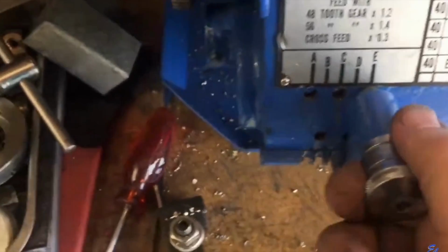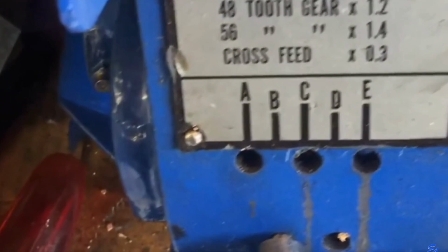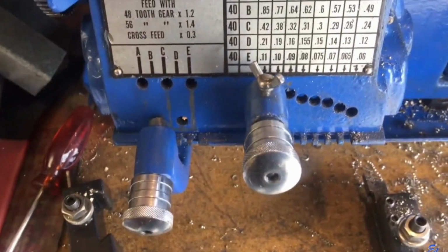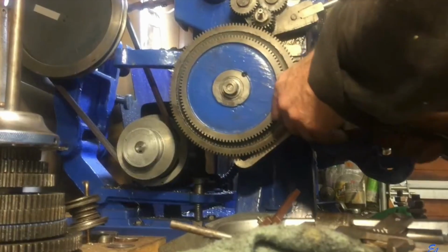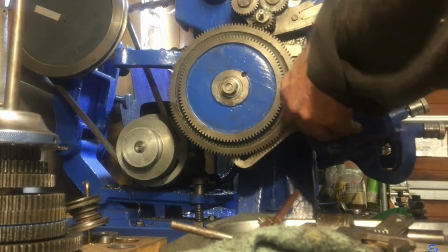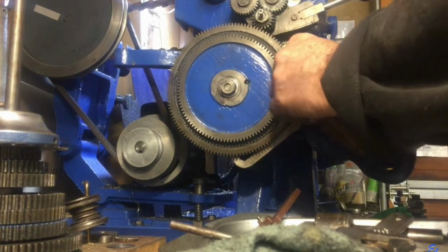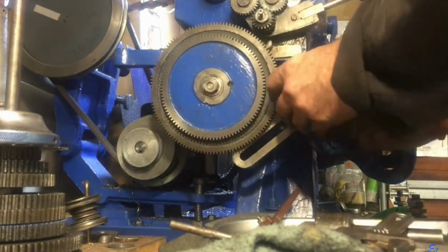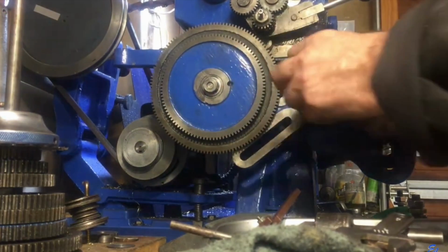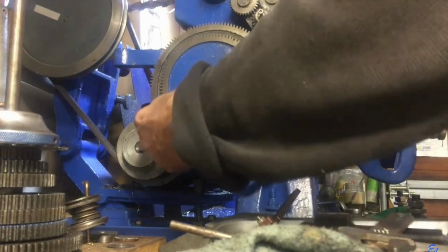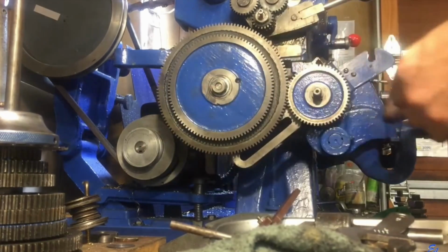So now we need to set up the gearbox for a setting of B1, so the left-hand lever goes to position B, and the right-hand lever gets moved to position number 1. And this should give you the gear ratio you need to produce that thread. It may not be 100% perfect, and it'll say on RideTheGearTrain what the amount of error is if you're not able to get a perfect thread. Often the errors are quite small though, and you can tolerate a small amount of error. Most bolts only have 5 threads on them, so there's not that much problem accommodating a little bit of variation.